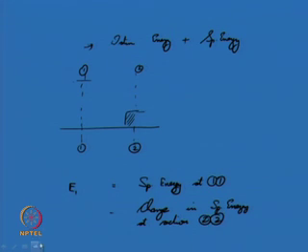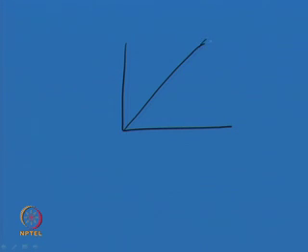So, we will see what the change is. Again go back to your E versus Y curve. So, this was your depth of flow Y1 at section 1, and the corresponding energy E1.